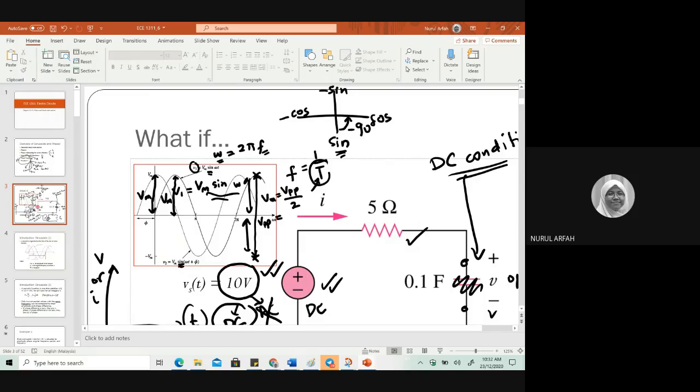If you look at the signal V1 here, we have Vm sine omega t. And if you look here, this is a sine, right? There's no positive or negative in front, but you know that this is a plus sign. So if you look at this graph, because we want to focus on cosine, we want to have everything in cosine form. Then from sine to cosine, you need to minus 90 degrees. So this is actually equal to Vm cosine